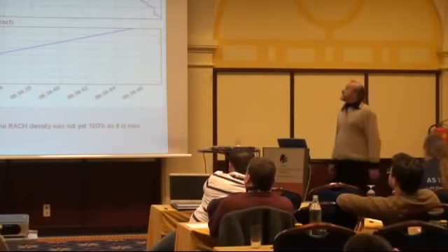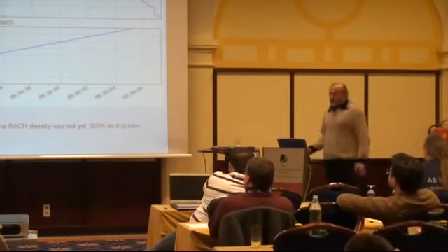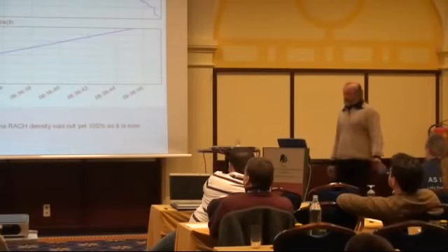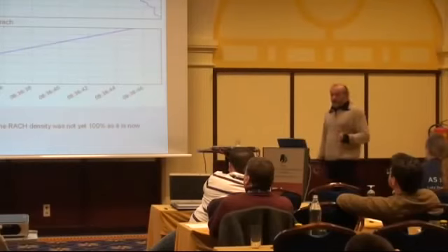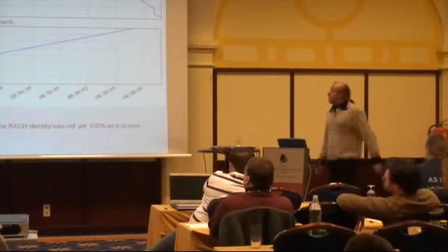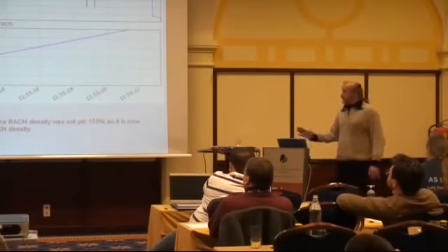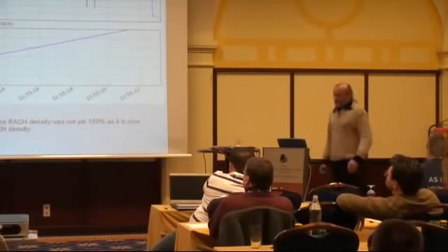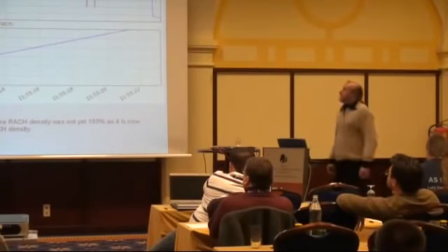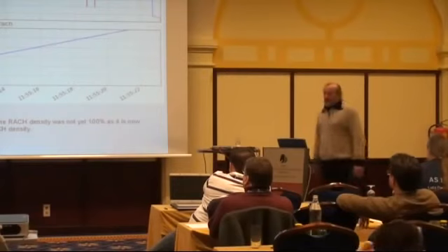Those are those drops in the diagram. At every drop, the base station controller checks, are there any channels which have expired? Let's free them. In the next diagram, it's rather similar, but a different BTS, in this case 4 TRX, 40 channels available.